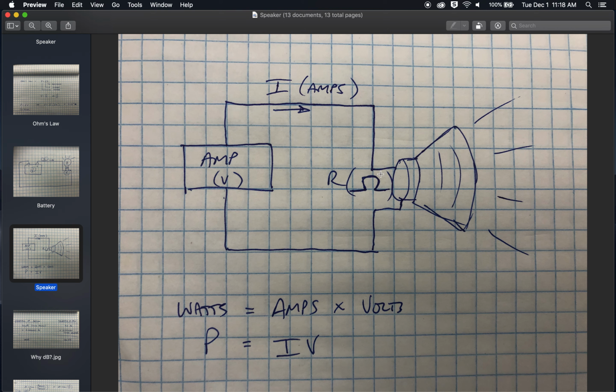So there's a lot of power coming from this amplifier going across this speaker, and you can literally, over time, because there's so much air pressure being pushed through this speaker cone, you're either going to get very, very minuscule holes developed in this, because it's mostly just paper. Some of them have like a Kevlar kind of coating, but it's basically just heavy paper, and so little holes can develop over time,